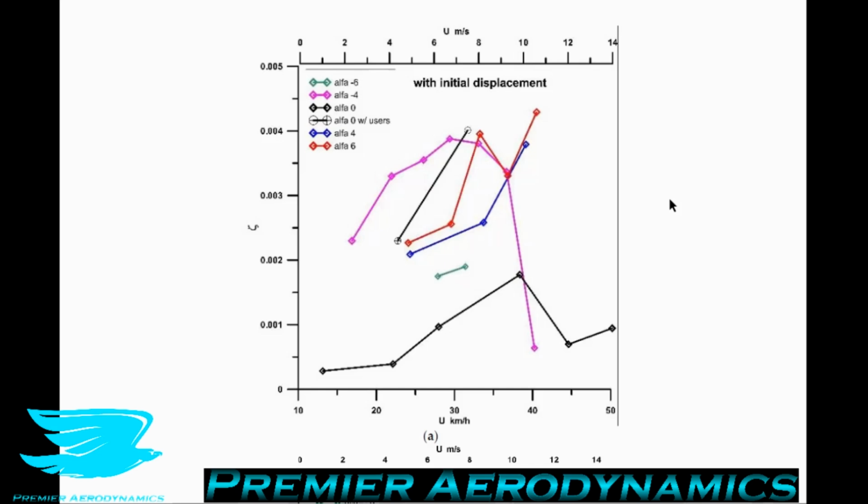If you have positive damping, it means that it's trying to clamp down on this phenomenon and stop it from happening. So positive damping is good. And this bridge is displaying positive damping, which means that it's not allowing these aeroelastic instabilities to occur: the divergence, galloping and flutter.